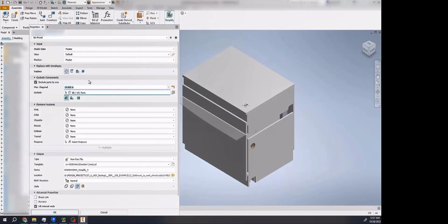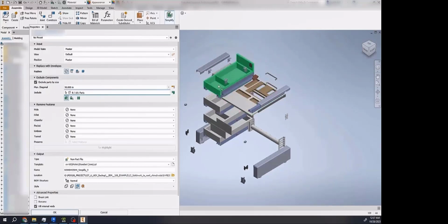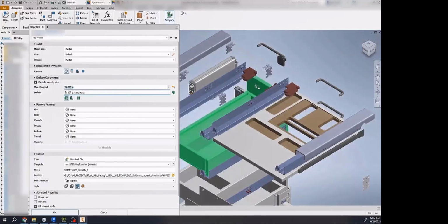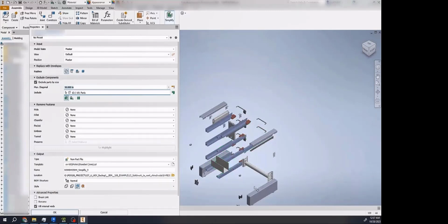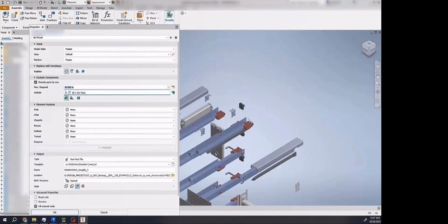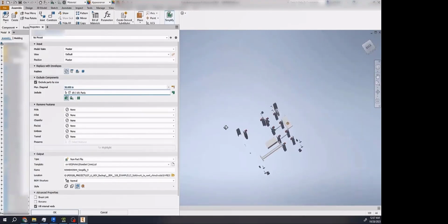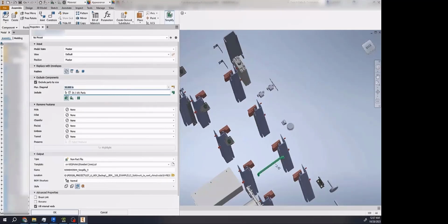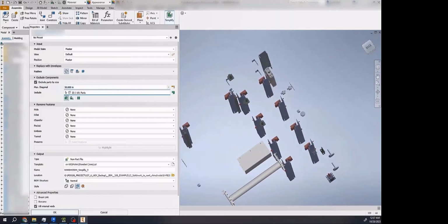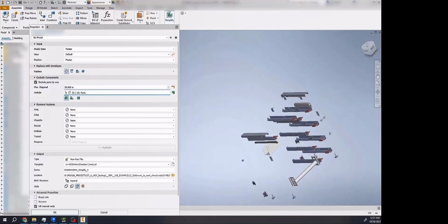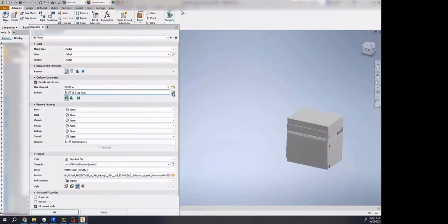Here, if you type, for example, a certain range of dimensions, it filters out the parts that you want to exclude from the geometrical export. For geometry that you don't want to exclude, you can include it by clicking those parts, so that we can control which one is going to be excluded and which one is going to be included. For me, in this case, I just exclude all those hardware and fitting parts, and then I'm happy with it.